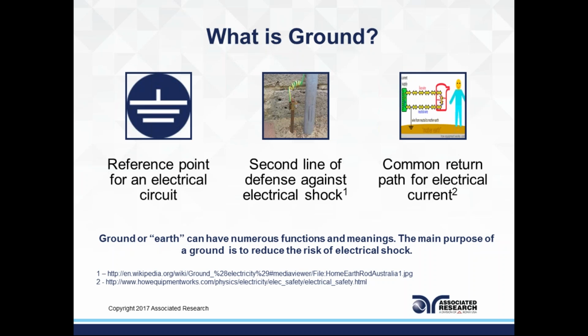If the charge was built up in your product or station or system, this provides a proper path for the discharge of this buildup of charge. And I mentioned earlier that it could also be a common return point. So a ground is not only a safety mechanism, it could also be a return point for a circuit. So when we're talking about ground in the household, we're talking about ground as grounded to the main input of the building.